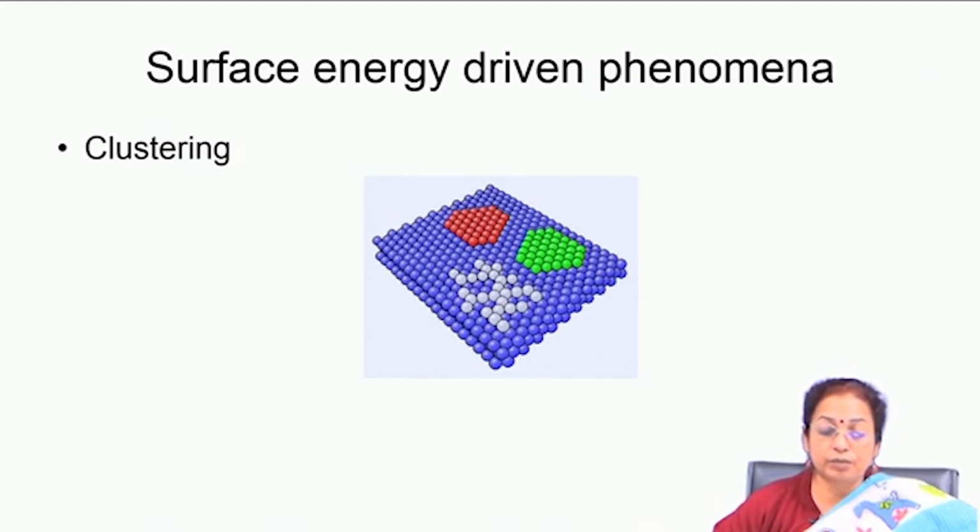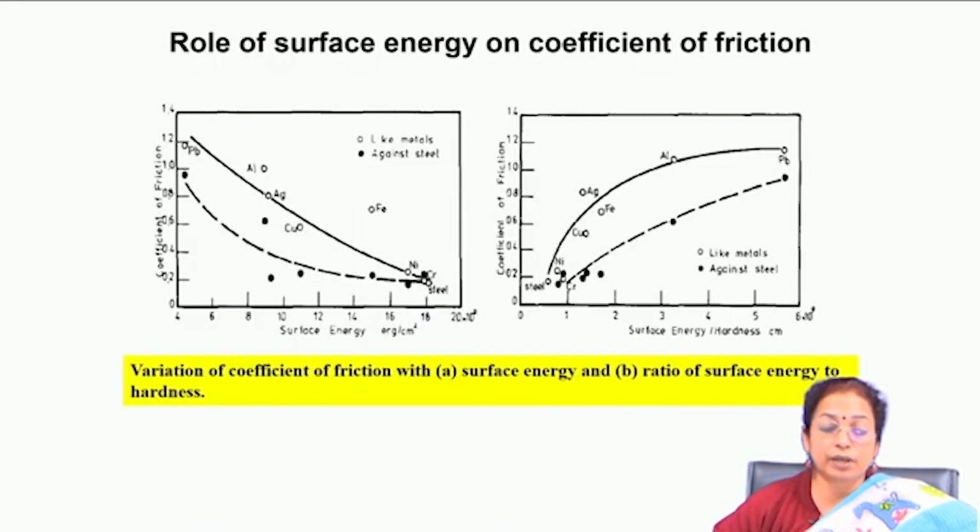If you think of bulk metallic material applications, whatever happens on the surface might not have a significant role, but if you think of applications of smaller structures, particularly MEMS devices, you will find that this change in atomic arrangement or composition might have a significant role on the functional properties of the matter. Structural properties like coefficient of friction and corrosion resistance are also influenced to a large extent by surface energy.